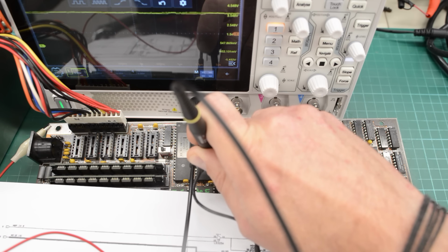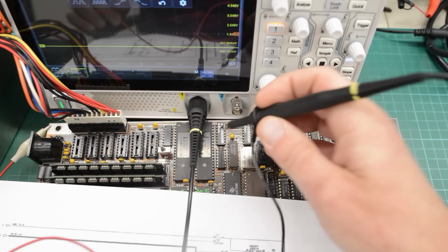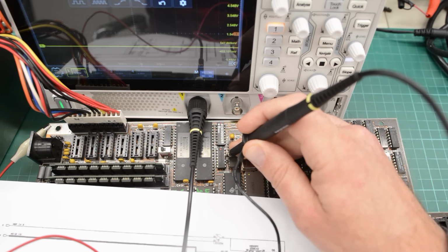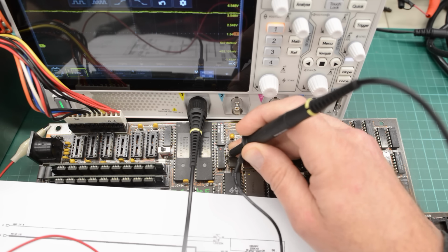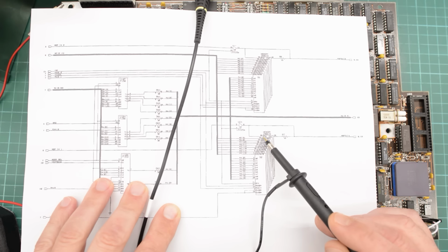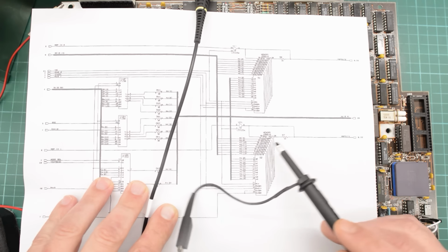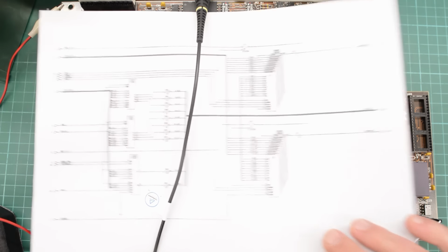Okay, it just goes high. So let's find what I think is pin 11. And here's pin 11. Let's boot. It just goes high and stays high at roughly 3.5 volts. Pin 21 here seems to invert whatever is coming in here. And I can't quite make out which pin it's hooked up to. It's just a blurry black mess. So that didn't really tell us much.